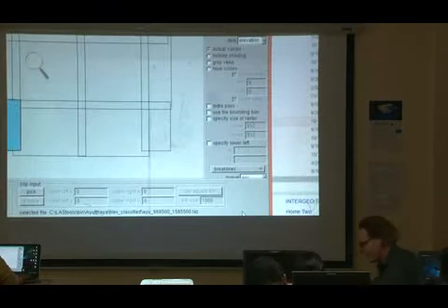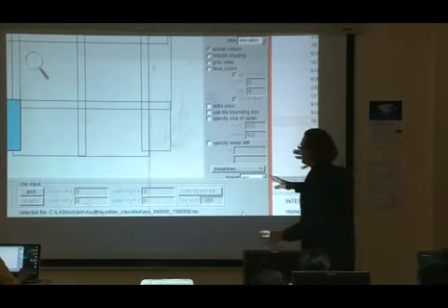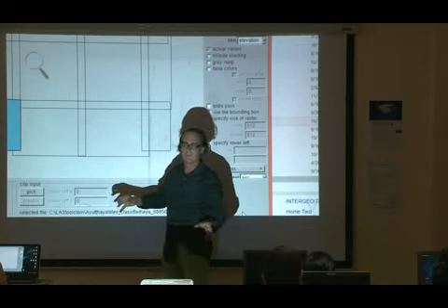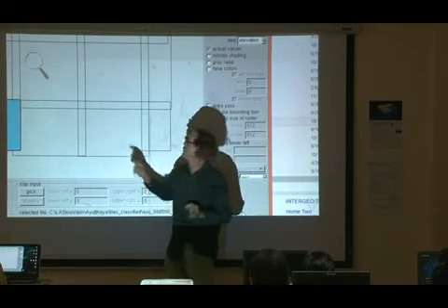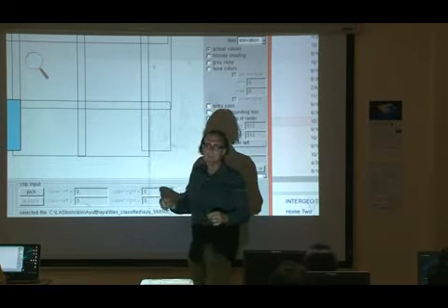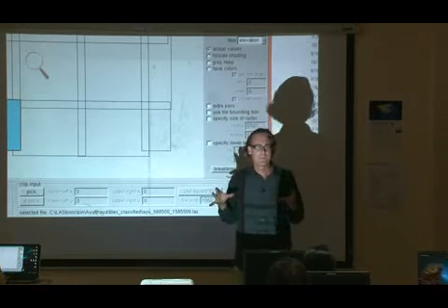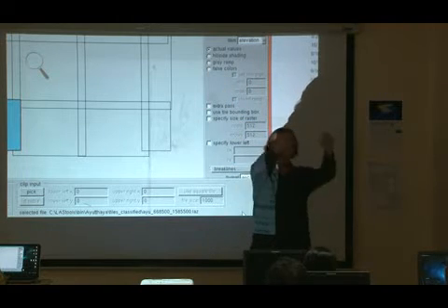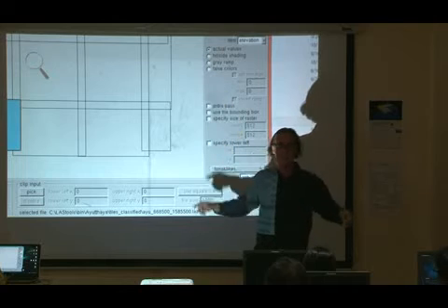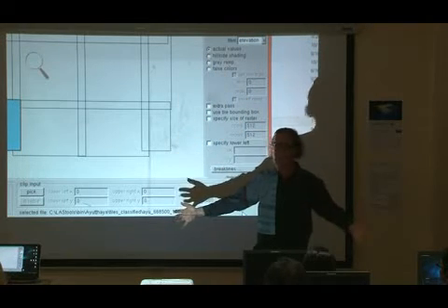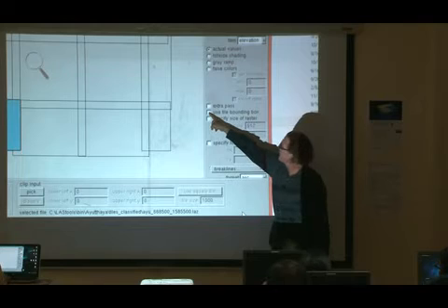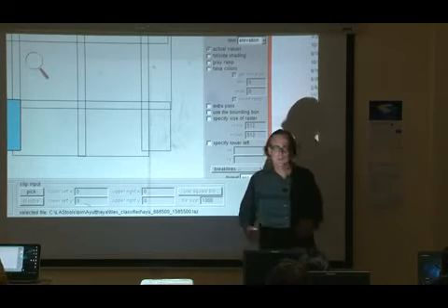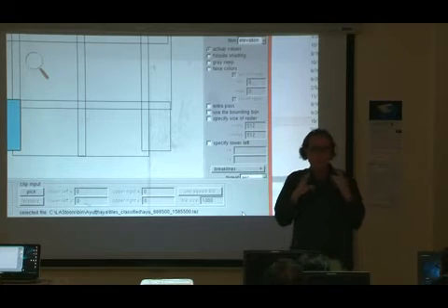And now, very important, all our tiles still have buffers, a 30-meter buffer. In the DTM, I don't want to use the points from the buffer. That's really cookie cutting now. I will make the TIN with the buffer. That's like making the dough. The TIN will be the buffer TIN of all the ground points. And then I'm checking this checkbox that says use tile bounding box. That means the real tile bounding box, the one without the buffer.